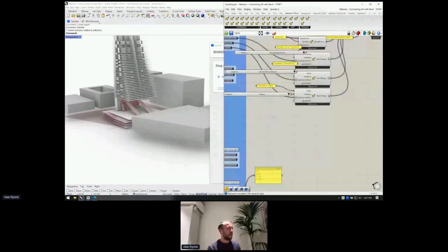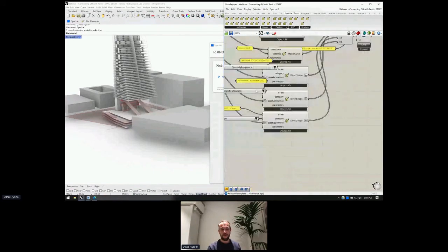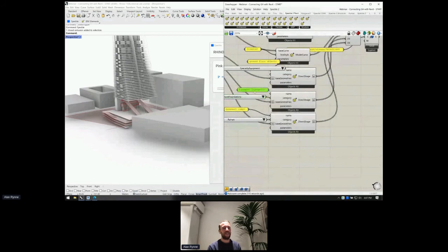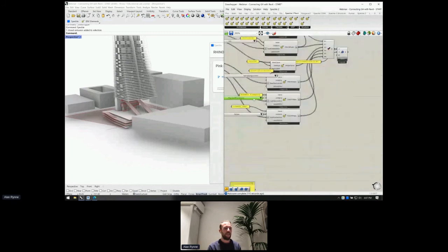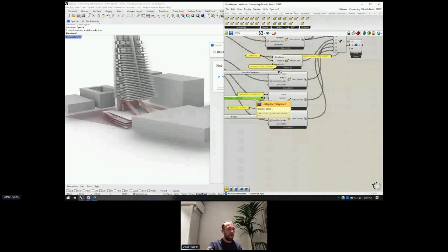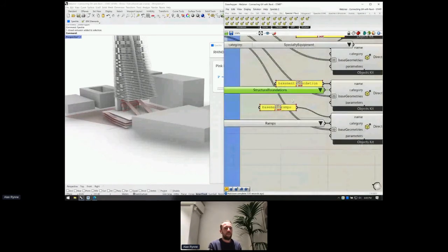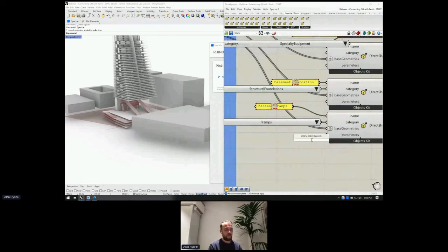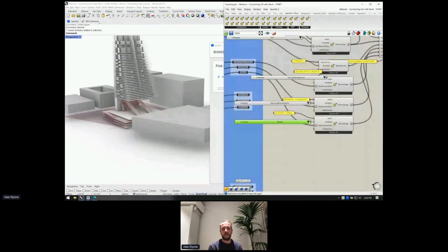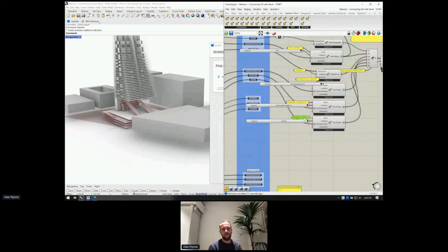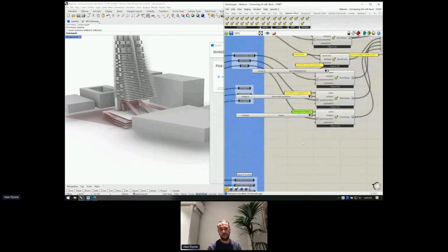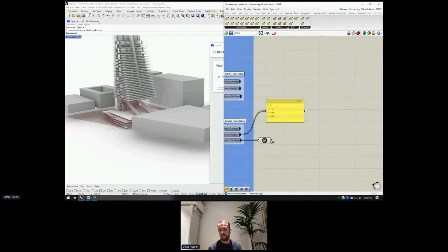I'm not sure about the model in place terminology. I've been away from Revit for a bit. But as far as I'm aware, we are creating them like literally just a raw imported geometry that you're putting somewhere, and you can attach any category to it. If that category exists, even if we don't have it in this dropdown, you would still be able to grab it. This is just a numerical value pointing to the categories in Revit. So if you know that numerical value, which you can easily get, you're good to go. We also have a trick to fix this further along in a couple of minutes.